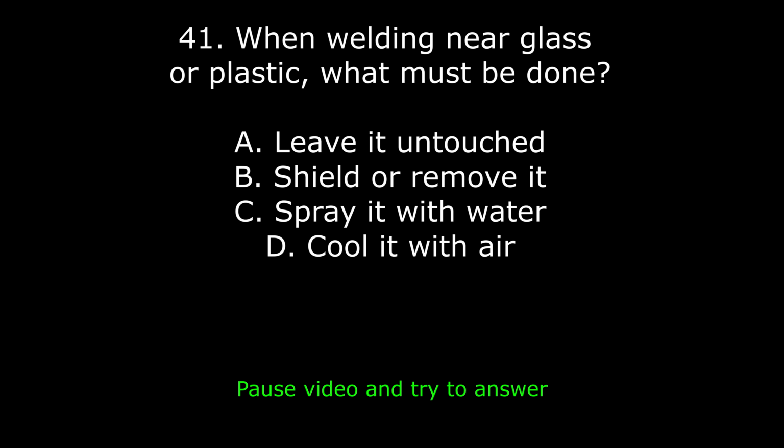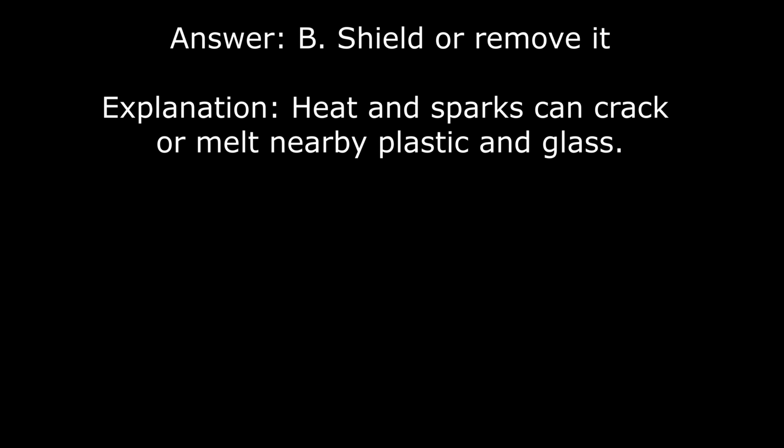41. When welding near glass or plastic, what must be done? A. Leave it untouched. B. Shield or remove it. C. Spray it with water. D. Cool it with air. Answer: B. Shield or remove it. Explanation: heat and sparks can crack or melt nearby plastic and glass.